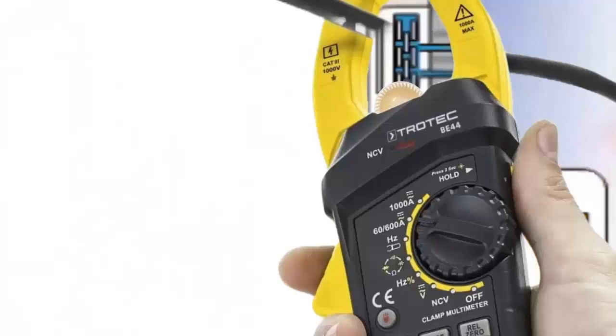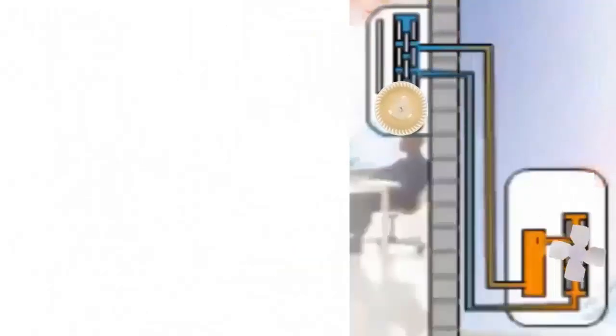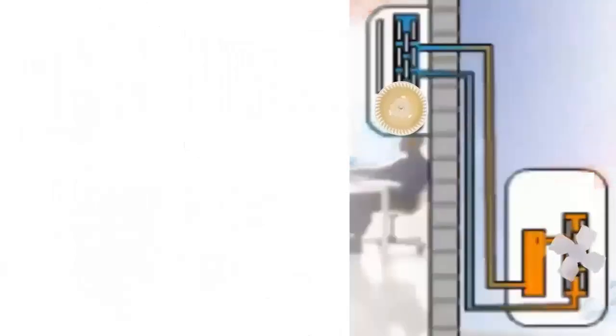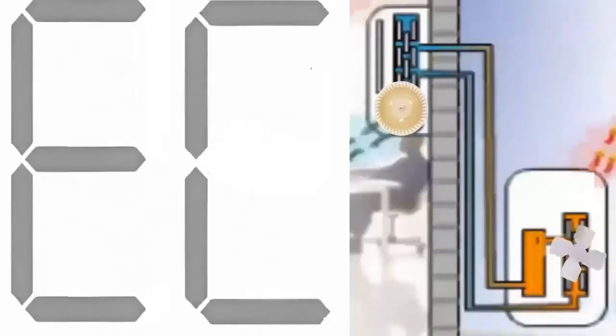D. Check the temperature sensors. A faulty sensor may trigger this error. E. Repair the leak and recharge the system with the correct refrigerant. F. Ensure that the refrigerant pressure is correct.